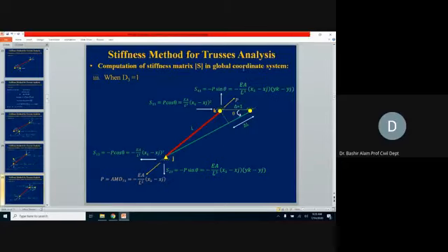Third, now corresponding to D3, here you see. We are sliding joint K to the right now. So this green is the new member now. Here now, if you see, we see an increase in length, which is because of the tensile force. So here you see P is shown away from the joint, meaning this member is going to come in tension. A similar process we repeat for this one. First we find out the member force, which is given here, and then we find out the member end actions, which are the elements of the stiffness coefficient matrix.